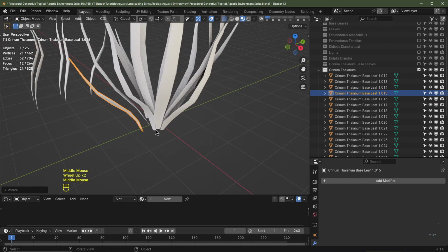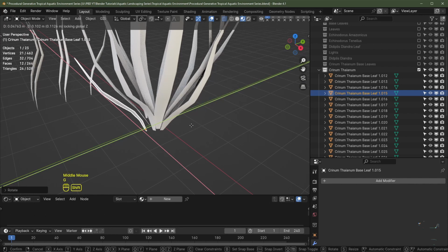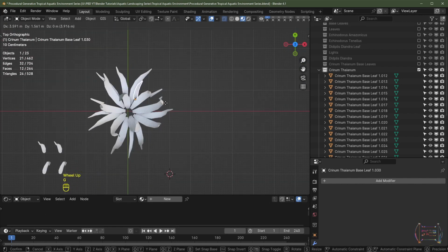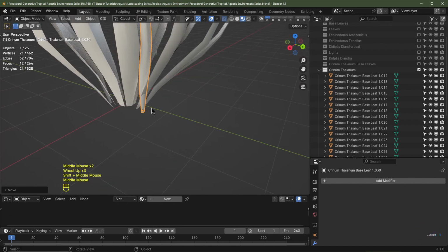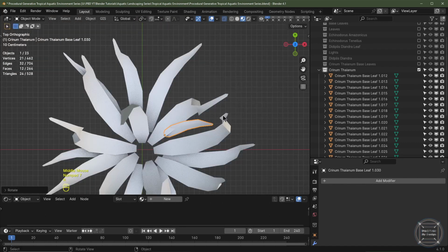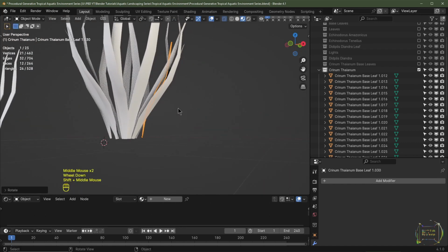Maybe I can bring it in a bit. G, Shift Z, bring it into around about there. Okay, then we use this one. G, bring this over to here, hit R to rotate, bring it in over to there perhaps. I'm not happy with that position, so G, Shift Z, bring it to around about there, R, bring it round, and then from this angle, I'd hit R.